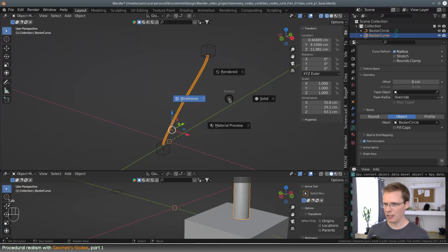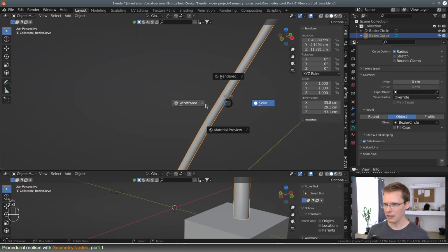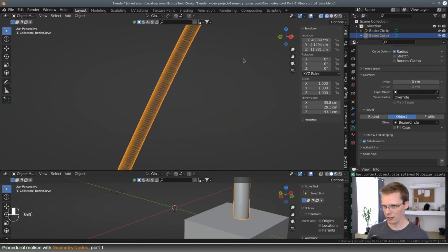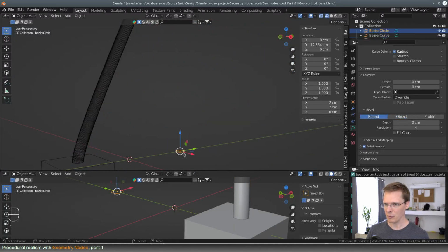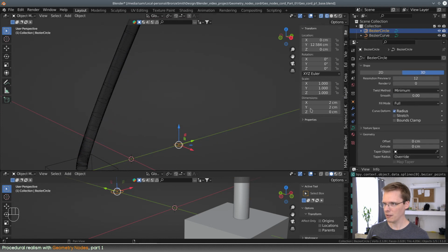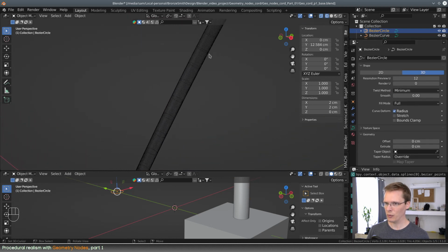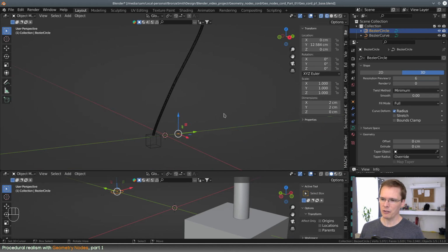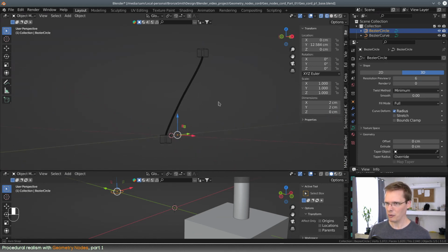So you set that all down. Again, it's procedurally generated. There's a lot more detail here just because the curve here has a fair amount of detail. And if you went to the curve properties for the profile, you can change how detailed it is. So curves have a lot of potential, but we want to do something more realistic than that with this particular curve. So we have to go about building a geometry nodes for it.